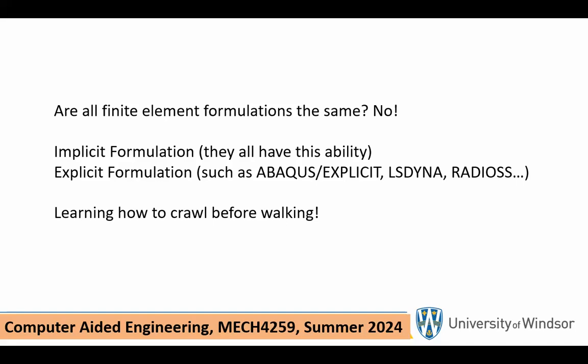Implicit solvers are the most commonly used, because they meet the needs of maybe 95% of the industrial applications and even academic usage. But explicit solvers are for specialized problems, to handle problems which are of short duration and extreme nonlinearities and extreme contacts, such as what you see in, for example, car crashes or stuff like that.